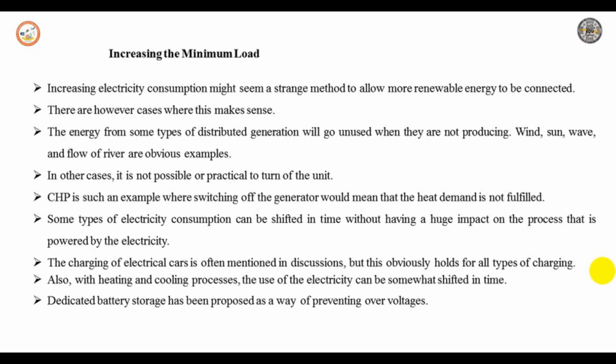So there are a number of methods for linking the excess of production to increase the load. Direct communication between the production and consumption is possible. This has been proposed as a way of using solar power to charge cars. The charger would normally operate below its capacity, but when the voltage at the generator terminal gets too high, the charging process is accelerated, so as to reduce the voltage. When this is still not enough, the production is reduced. Another option is to use